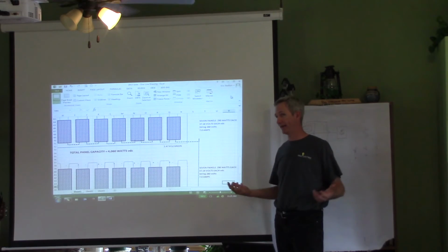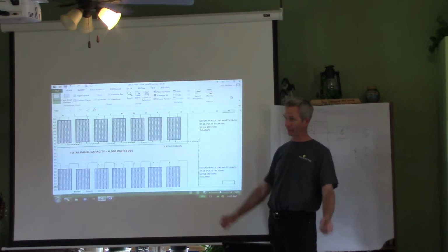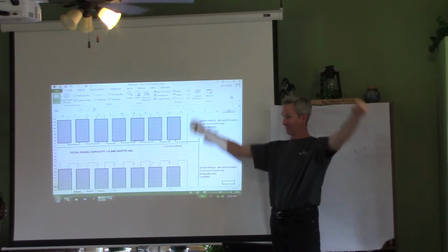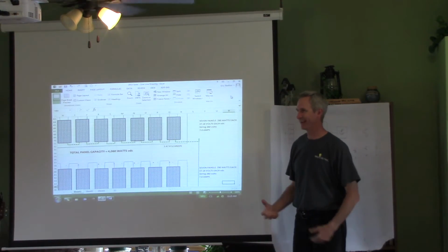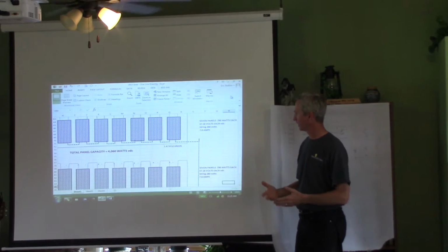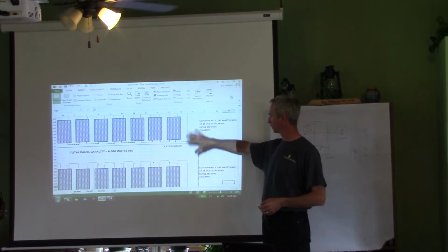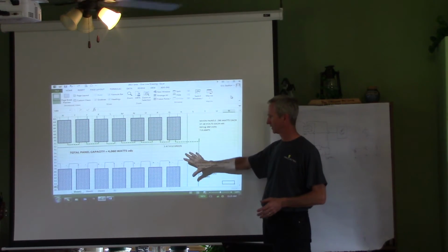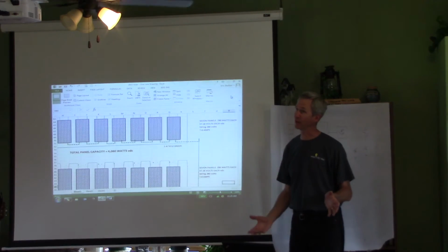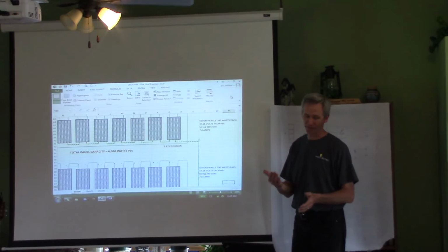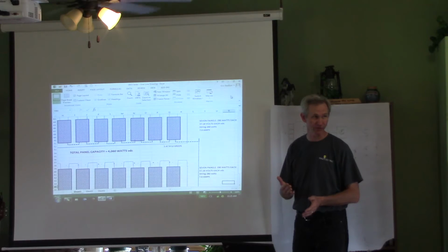That was one thing I did not understand. Like, well, grab some panels, plug them in, and let's flip her on, baby. Well, you got to balance it. So then they said, okay, well, we'll just cut this into 2 strings. That'll lower our voltages, get us in the right range. And again, there was a balance there too, because when we cut it, we had to still hit the turn-on voltage.